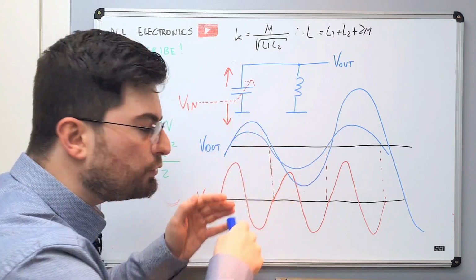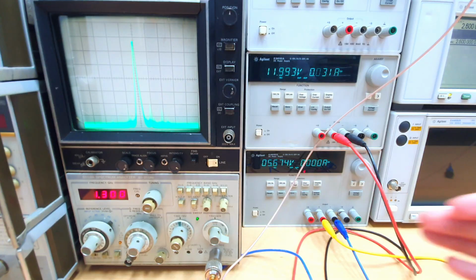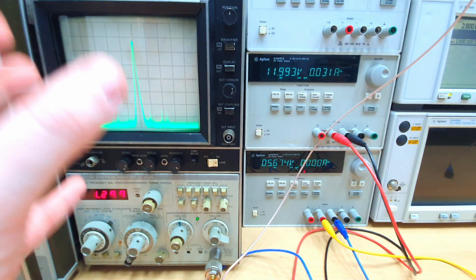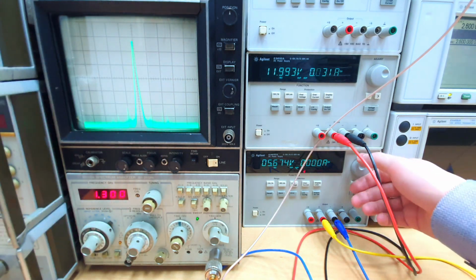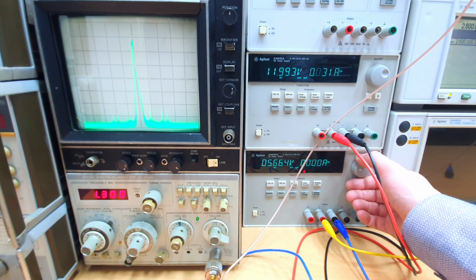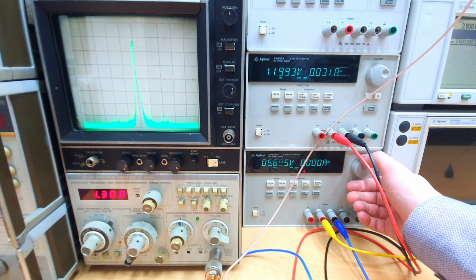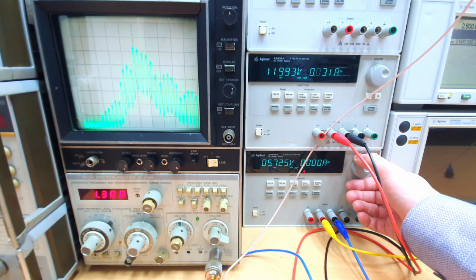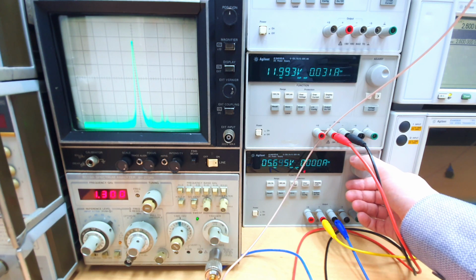This is parametric oscillation. Changing the bias voltage of the oscillator varactors, we can clearly see the behavior of injection locking by parametric modulation. Here we are injection locked, and we can go out of injection by changing the bias. Here we are getting far from injection, and here we see only parametric modulation without injection. We are entering injection locking. Now we are injection locked.